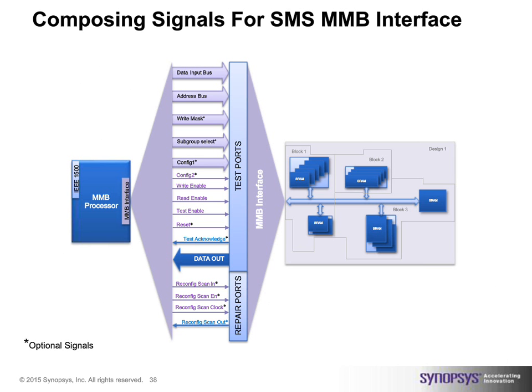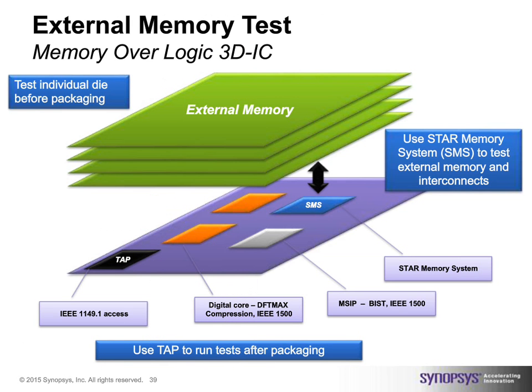Another element that we are seeing in our chips today, in these complex chips with FinFET, is the fact that there are some DRAMs, some external memories, that are sitting outside the chip. Those external memories need to be interfaced. But the fact that the chip is fast, and especially the interface itself is fast, let's say it's DDR4 or HBM or wide I/O, it is hard to intercept the signals between the green boxes and the SoC sitting below. What you need is an engine that sits in your SoC and from there interacts with the DRAMs that are sitting outside, or SRAMs for that matter.